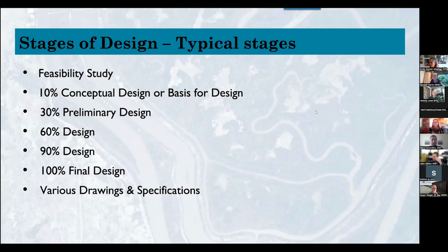implemented project. And always in projects, we have these different stages of design. We start off with a feasibility study, ideally then goes into conceptual design, and then increasingly detailed engineering design, and which also needs to get approved by regulators. And then that develops into a series of drawings and specifications to then put out to bid to a contractor. So that series of stages of design is really important.